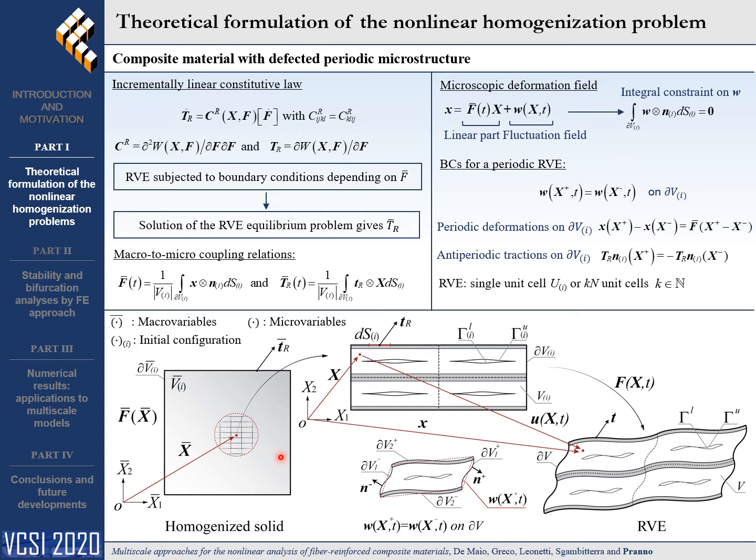This domain may contain cracks whose opposite surfaces may undergo frictionless self-contact. Each constituent is characterized by an incrementally linear constitutive law relating the rate of the deformation gradient tensor to the rate of the first Piola-Kirchhoff stress in terms of the tangent moduli tensor. The RVE is subject to boundary conditions depending on the macroscopic deformation gradient, and the solution of the corresponding nonlinear equilibrium problem gives the macroscopic first Piola-Kirchhoff stress.